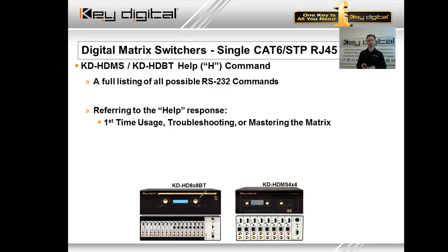Okay, so the first time you get your hands on the product, you're going to want to plug in and see this. You're going to want to become familiar with it. Troubleshooting. Hey, I don't have video from my source 1 at all. I don't have a blue sync light. Well, we may ask you, can you go in, can we terminal in this product? Let's toggle, maybe you're selecting CAT port instead of HDMI, or vice versa. Or mastering the matrix. There are a lot of extremely cool features to this product.